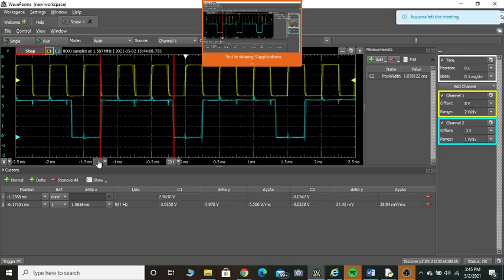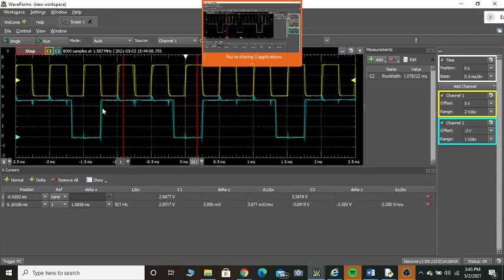You can see you applied one trigger signal. Whenever I apply this trigger signal, what is the state of your output? Whenever I give this, just see this. Whenever this is coming, was the output in stable state? Since the output was in stable state, it considers this as a valid trigger signal. It is there up to the predefined time of 1 millisecond. Within 1 millisecond, if you get a second trigger signal, third trigger signal, it will not consider that, because the output is still in quasi-stable state.